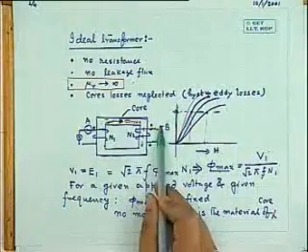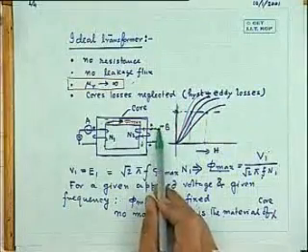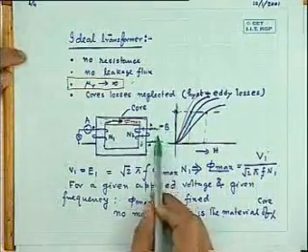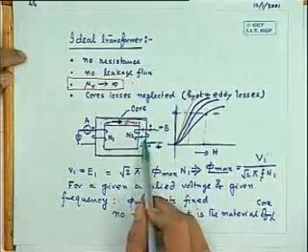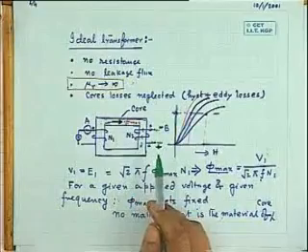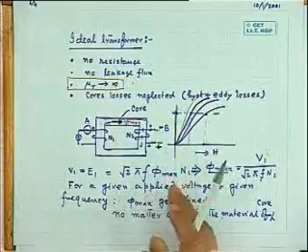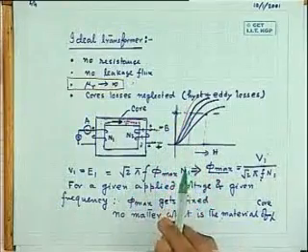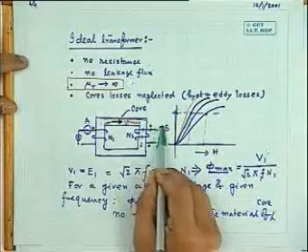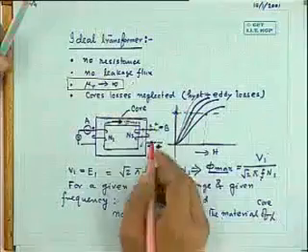The cause was that flux was increasing in this direction. Now, if for argument's sake, let us assume this is plus, this is minus, then this EMF, if it is allowed to act in an external circuit, will create a flux which will further aid that cause, which is negating Lenz's law, which is not possible. Let us see the other possibility then. Suppose let us assume this becomes plus, this becomes minus.